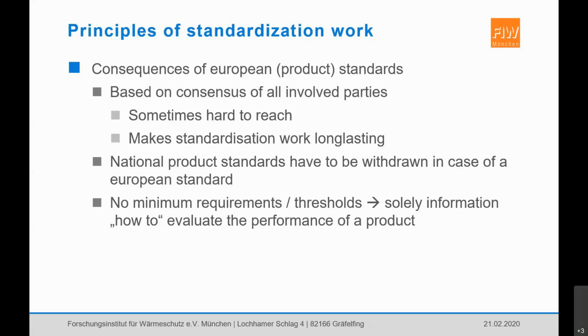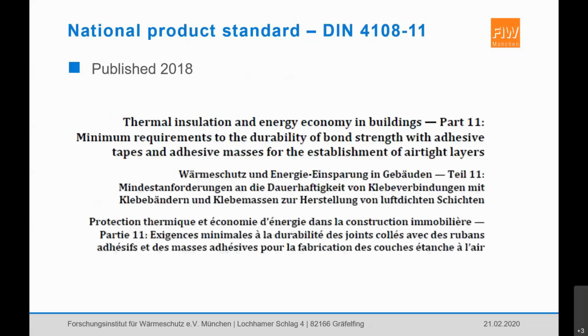Okay. Let's go to the already introduced national product standard, the DIN 4108 Part 11, as an example for a product standard for airtight adhesive. It was published 2018. You can see here the title, and if you have a look at the title, you see that it already indicates that the main focus is on the durability of the bond strength.